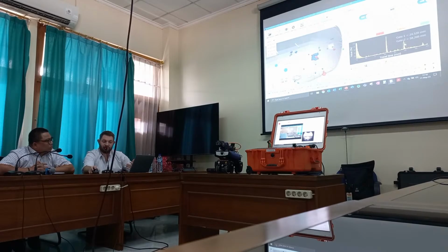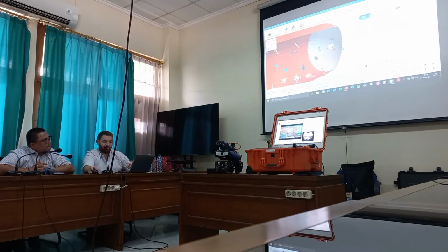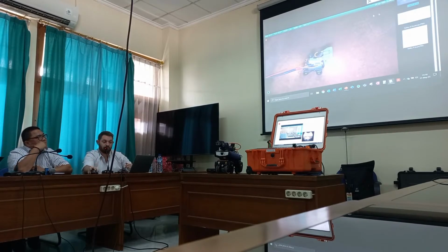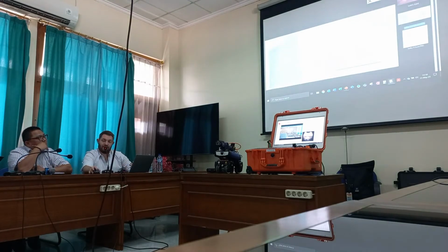If we want to see some other forms of NDT, we've actually mounted a digital pit gauge to the top of this. So we were going through doing surface profiling in some areas and looking for pits, or measuring the pits using structured light technology. We could then create a heat map from those scans, and also our visual surface profile as a picture.